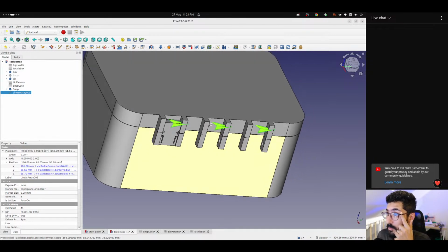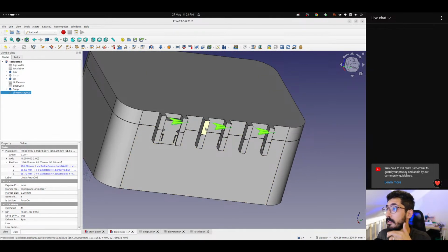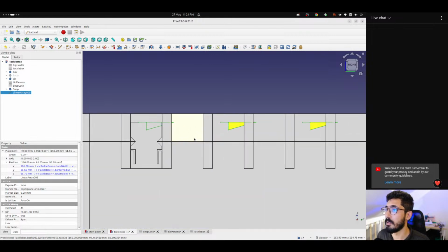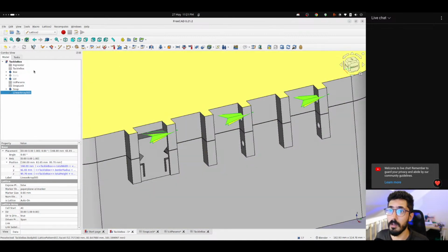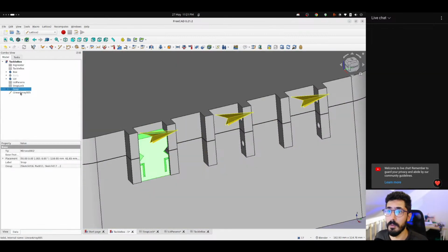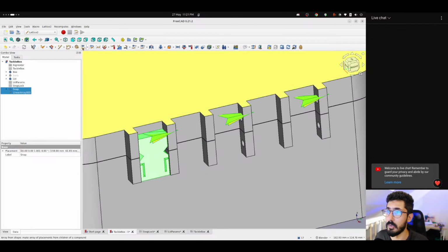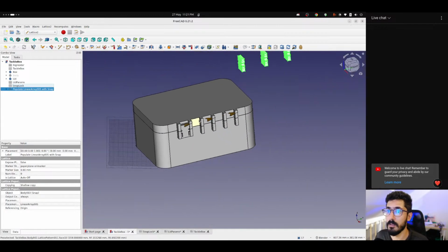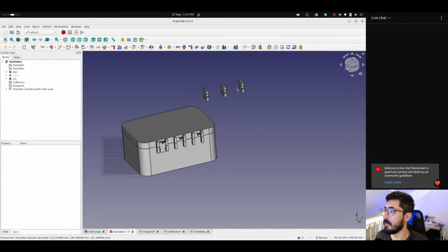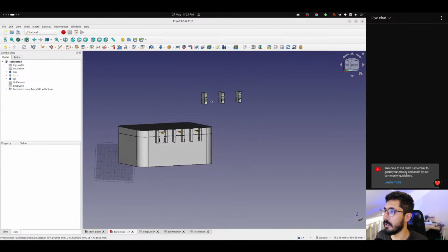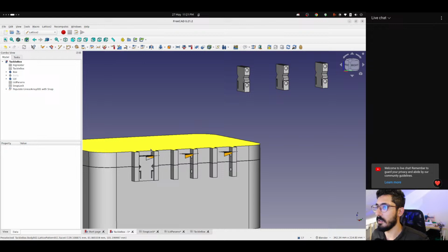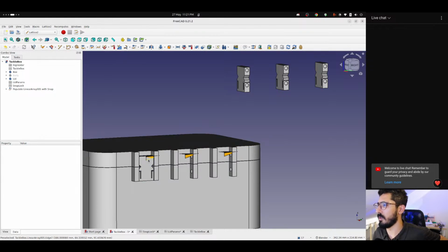Okay, so now how do we take this and populate it with copies? If I just click the snap, control click the array and click populate with copies, it will be somewhere here. Because it does not know basically where this object starts or how it is oriented.